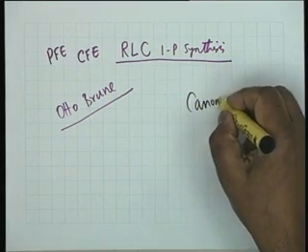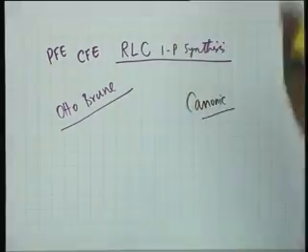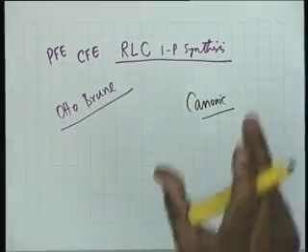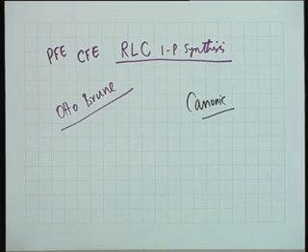You see, all the synthesis that we have been talking about so far, 2 element kind, is canonic. The number of elements is exactly equal to the number of specs, nothing more, nothing less. You cannot do it less, you can do it more, of course. Okay?